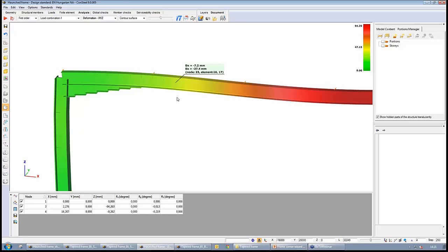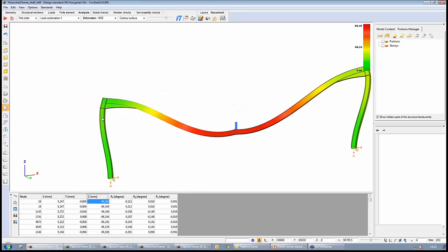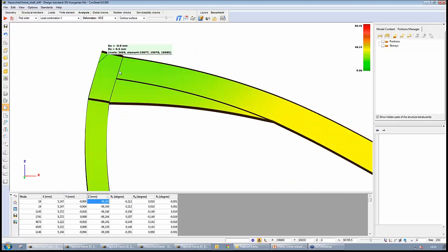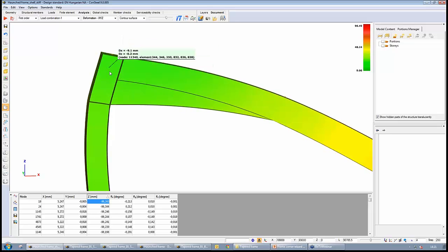and it is also a very affecting area of the out of plane behavior, so the lateral torsional buckling behavior of this frame, because these are the highest bending moment region producing the lateral torsional buckling. And of course in reality at this zone, the cross sections can be different, and secondly the behavior of these cross sections is completely different from what is calculated in the beam model.